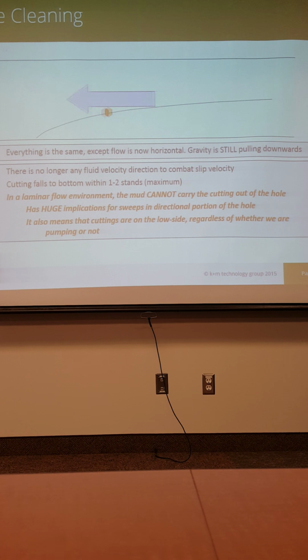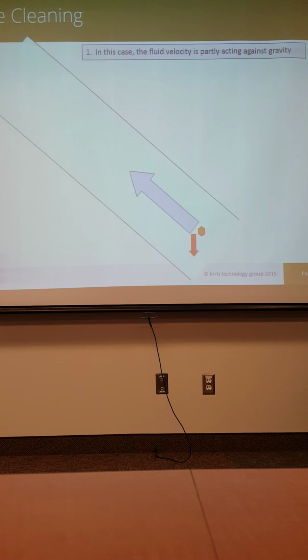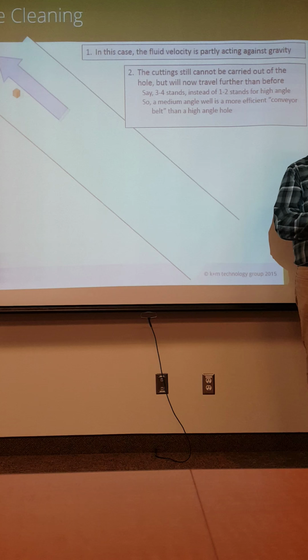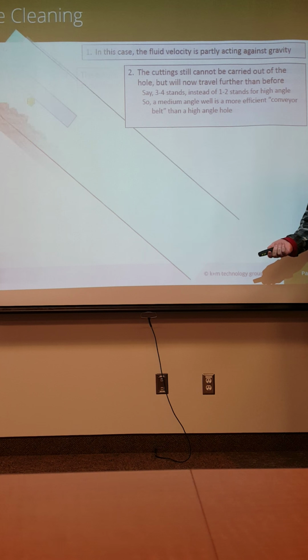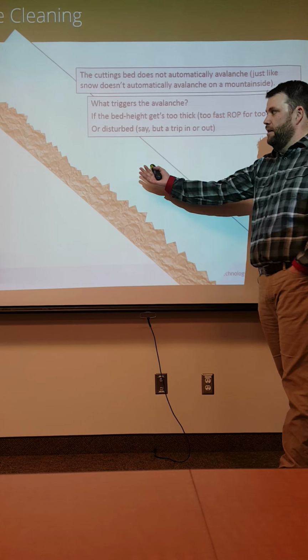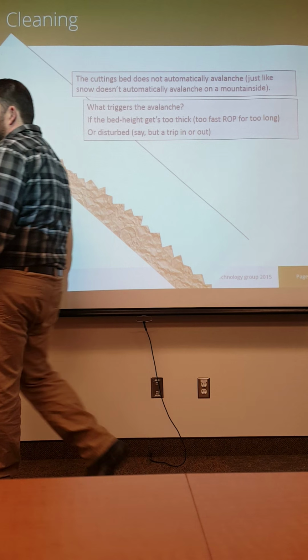So hole cleaning is most important before you trip. It's not that important while you drill. You can drill a filthy hole. As long as you're going that way and the cuttings are going the other way, you're fine. But when you go to trip, that's when it has to be clean. Medium angle wells, even before you shut the pumps off, you have to make sure the hole is relatively clean, because as you're shut down, the dirt's coming to see you. It might take 5 minutes, it might take an hour, it might take 2 hours, I don't know, but it's coming to see you. We know that for sure.